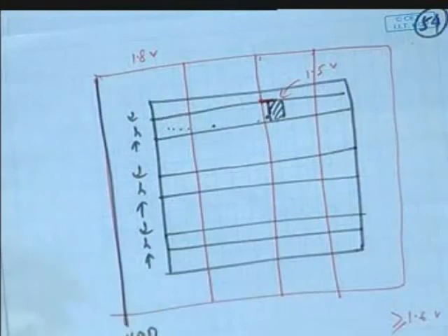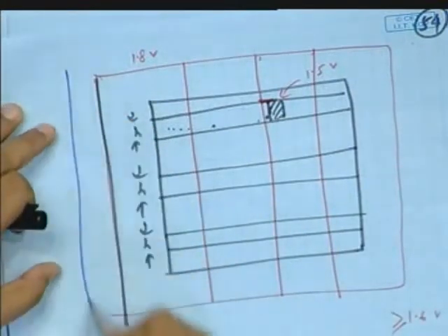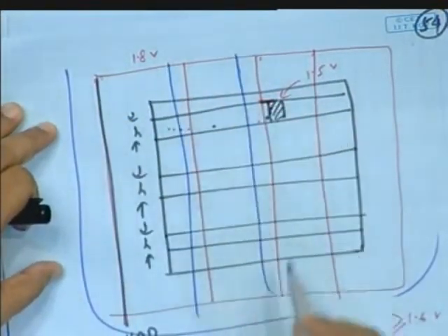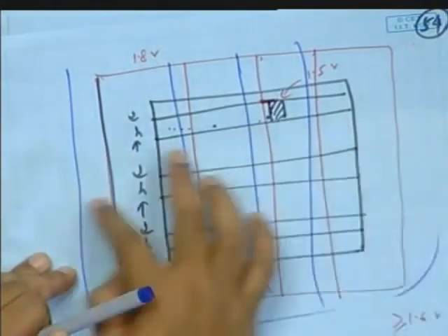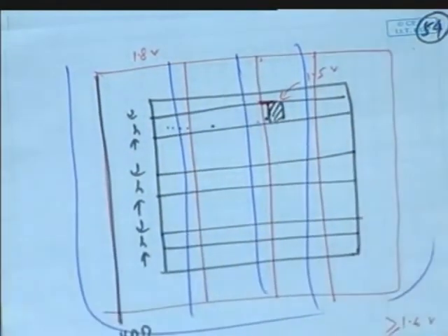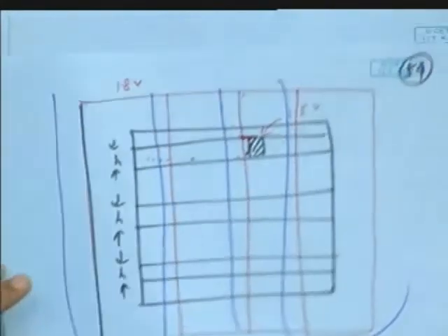So these are called power straps and power mesh, this is called power ring, okay. Similarly there should be some ground ring also. So when it will be here there should be some ground pin also, right. The ground is something like this, ground strap, okay. This power strap also you can make like this as well as horizontal. Generally we follow only one direction, okay. Once these things are done, so basically now you assume that your floor plan is ready to be placed, okay.